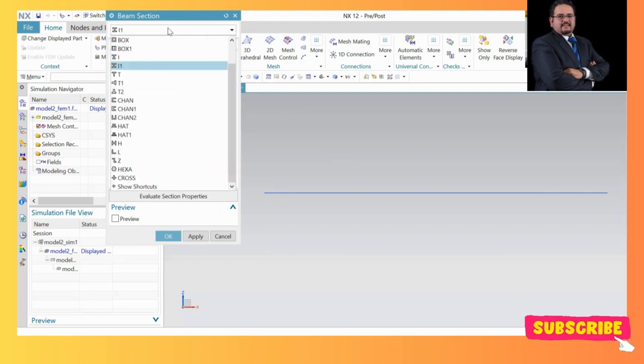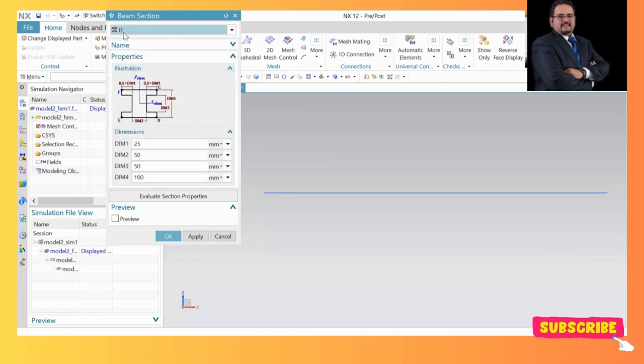If I click here, all these different types of cross sections are there, beam cross sections, right? All these options are there because I selected beam initially. So I can say that as per the problem, I am working with this I-type beam, and I have these input buttons where I can just put the values, and I can create the beam.